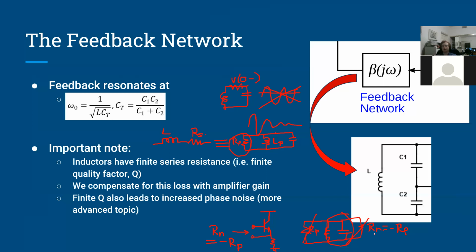Got it. And in all of this, we're really only concerned with the frequency of the signal. We don't particularly care what amplitude it ends up at for that frequency, as long as it exceeds our minimum logic levels. You do care about the amplitude. Do we particularly care about the final amplitude of the oscillator signal?